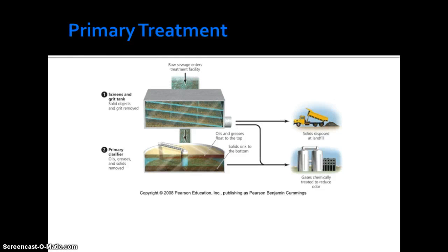For a closer look, primary treatment includes screens and settling tanks, which remove grit and suspended organic matter. As Anderson and Sheffield note, many facilities have primary clarifiers or sedimentation tanks. In this sedimentation stage, water slows down and large debris settles out due to the forces of gravity. That is, when the velocity of water drops, materials are no longer carried in the flow and settle out of